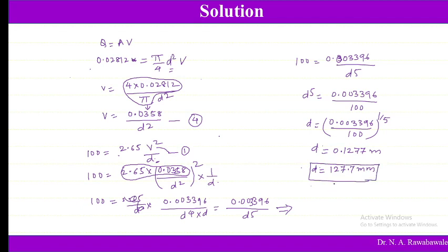Now the next thing left with us is the efficiency, which is equal to (H minus HF) divided by H. We know H is equal to 500, which we have obtained, and HF is 100. So this is 400 divided by 500. So this will be the efficiency of power transmission.